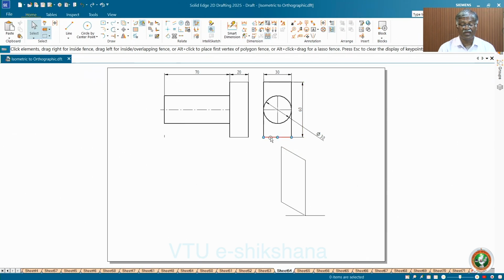So this is 30 mm on a 30-degree line. This is vertical 60. I am considering this as an isometric view only, then we will convert that by scaling it to 0.816. Otherwise, if you are doing it manually, you can do it by taking measurements by scale. Now I will do the isometric drawing, then I will convert.